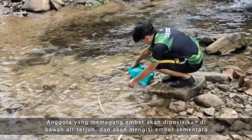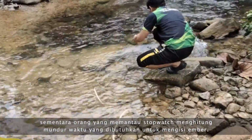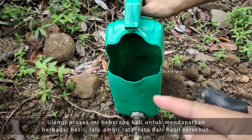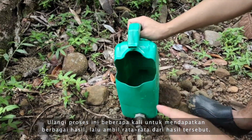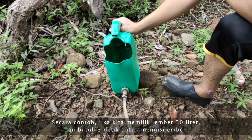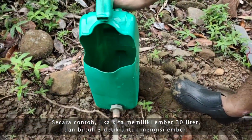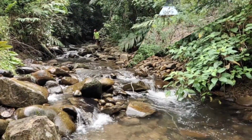The person holding the bucket will be positioned under the waterfall, filling the bucket while the person monitoring the stopwatch counts down the time it takes to fill the bucket. Repeat this process several times to get a range of results, then take the average of those results. For example, let's assume we have a 30-liter bucket and it takes 3 seconds to fill the bucket. This means we can assume the flow to be 10 liters per second.